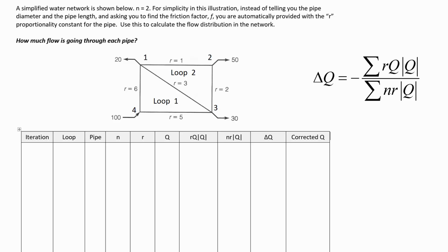We don't have updated guesses, and this will self-correct. The Hardy-Cross method is when it balances the energy, it's going to self-correct that. And at the end, let's revisit that. Let's double check that our solution, when we're done, not only has the right head losses, but also that it still is honoring continuity. Because any solution that isn't honoring continuity, we can throw out, and we know that it's ridiculous. But I see your point, but there's just nothing else we can do quite yet.